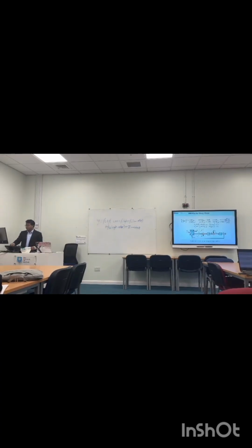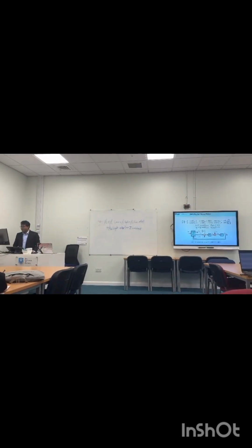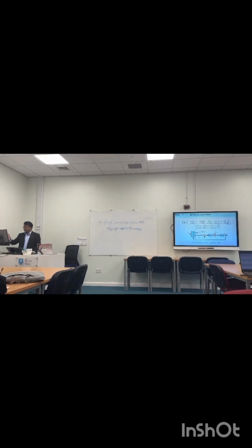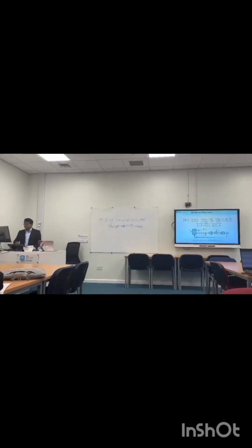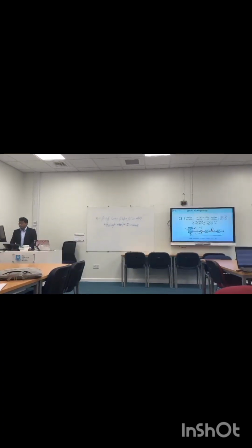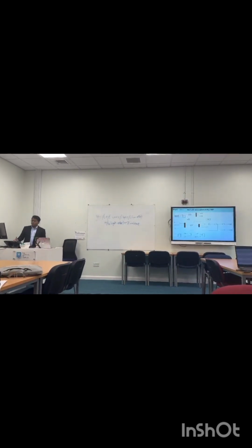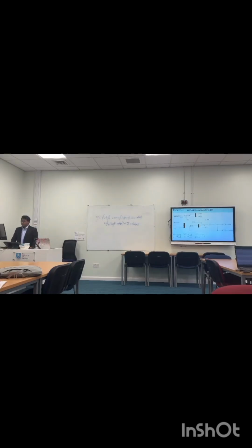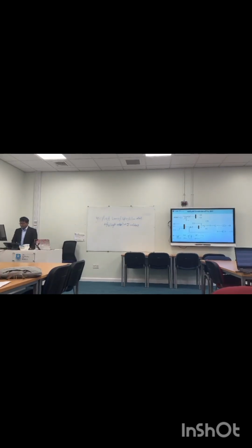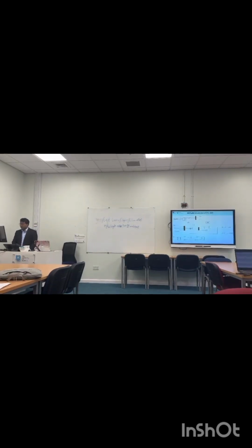And this is the synchronous reference frame PLL. As we said, the difference between the grid angle and the DQ PLL is always being corrected, and we are getting the D frame voltage and Q frame voltage. This is called the reference frame voltages. And I'd like to show you some simulation, which is the basic concept of this project.